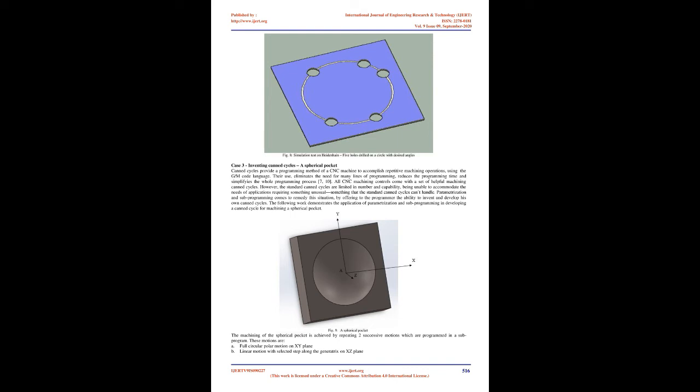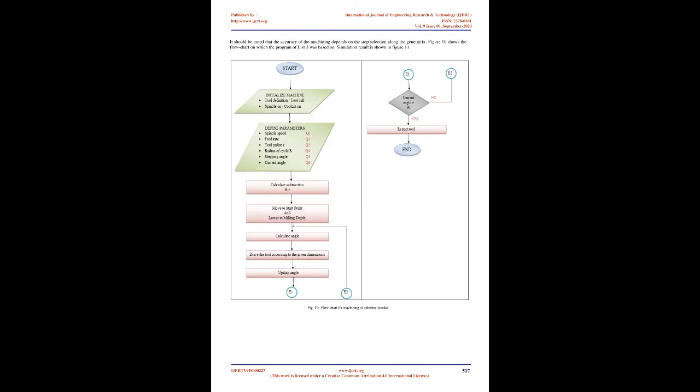Case 2, families of parts. A bolt circle. Almost all companies have at least some applications that fit into this category. Possibly they have prints dimensioned with variables right on the print. The programmer must reference a chart on the drawing to come up with values needed in the program. Or even if they don't have a perfect family of parts application, surely they have at least some work pieces that require similar machining operations. With parametrization, it is possible the development of general-purpose routines for similar machining operations.